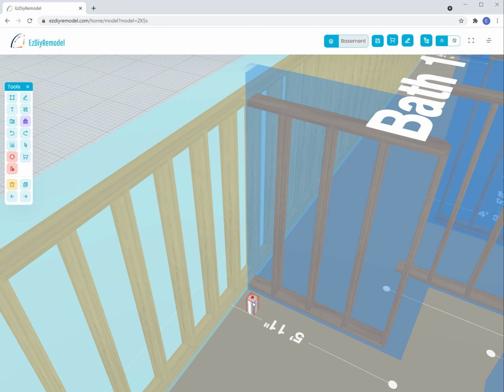Now, this main stack, in my case, you need to identify where it is going into the ground. This is where it starts for me. And then you also need to identify where it goes up to the first floor or down from the roof in the attic. You need to take all those dimensions so that you can model the house the right way. This is a very critical piece to connect the toilet and other main items that drain water.